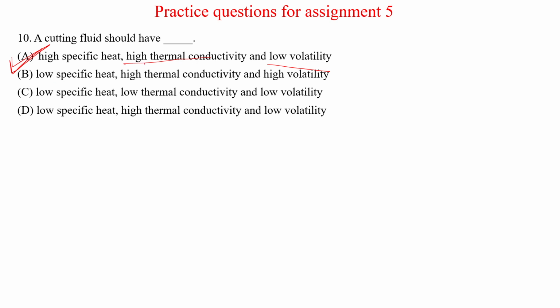Second, it should have a high thermal conductivity because we want the cutting fluid to not hold the heat. If the thermal conductivity is very high, then the fluid will not hold the heat, it will pass the heat on. So we require that. And third, obviously we require low volatility for proper stability. So it should have a high specific heat, high thermal conductivity and low volatility. Okay,